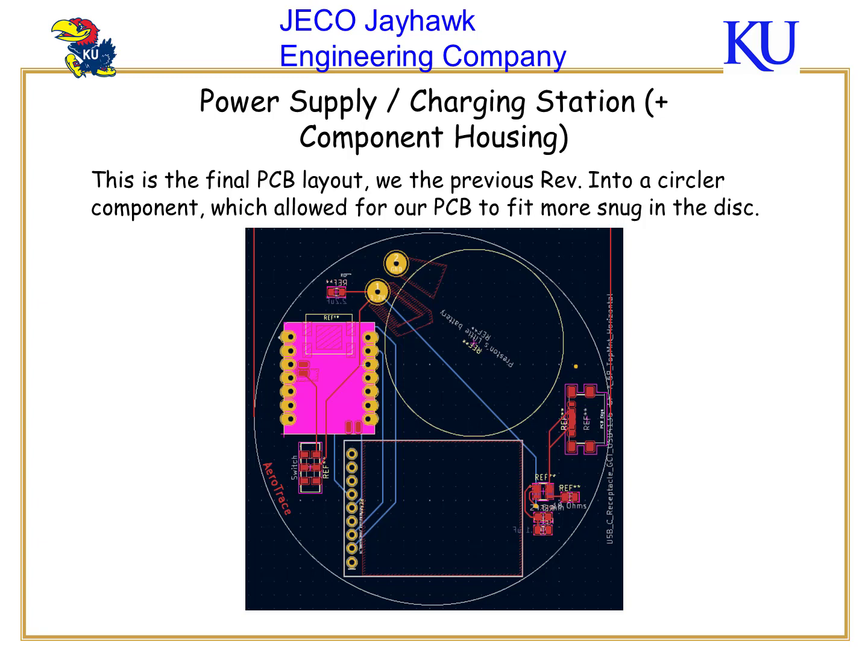When on, the battery powers the MCU, which in turn powers the GPS. When off, the switch creates an open circuit with the battery, meaning no current is passed through and no power is being provided to the MCU and GPS.